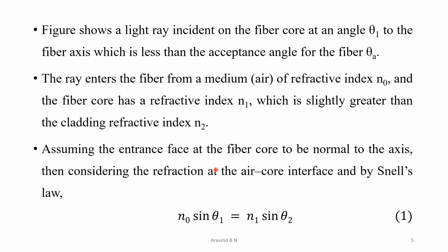Now getting into the actual derivation part. Assuming the entrance face of the optical fiber core to be normal to the axis, consider the refraction at the air-core interface. Remember, we are considering the air-core interface, so by Snell's law it becomes n0 sin theta 1, where n0 is the refractive index of the air and theta 1 is the angle of incidence, equal to n1 sin theta 2.